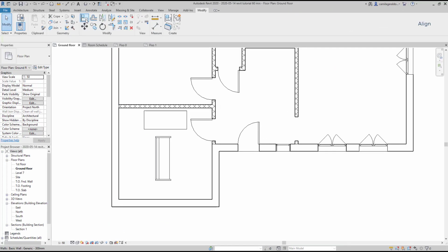Although with the Align tool, I do the same process as before, and this selection line is not the one I want, because the sofa would go inside the wall to match the center line. On the options bar, you can see this Prefer, and I can change the part used to generate the line of alignment. This time I want it to detect the wall face. Let's try.